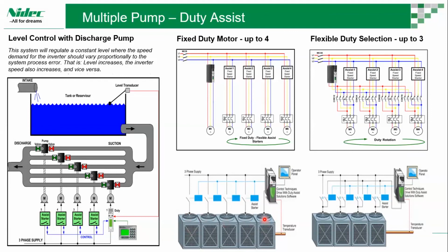Suppose we have a common drive used for all the motors. Here we are running at 100%, and again it goes to 100. This one is going with variable speed, so it is always less loaded, while this one is loaded high. So mechanical imbalance will happen, and mechanical stress on the pump or the system will occur. So the ideal requirement will be one drive, one motor.